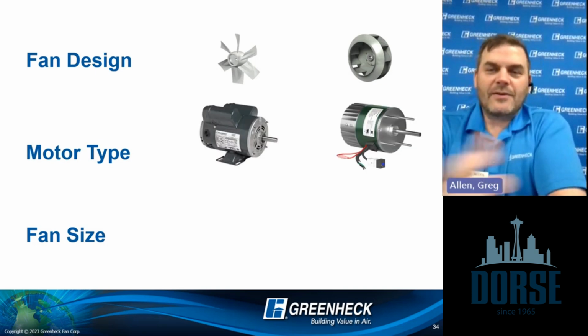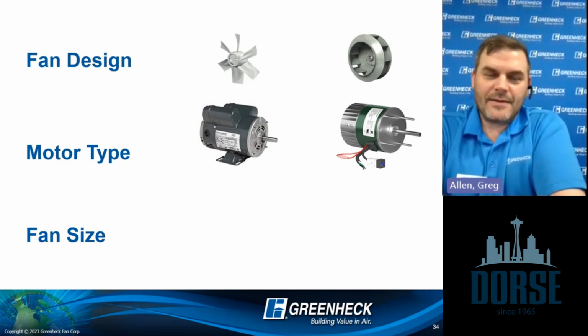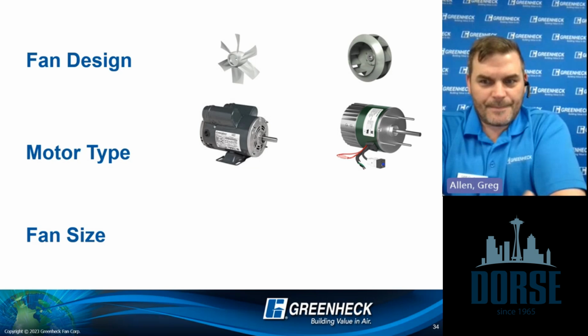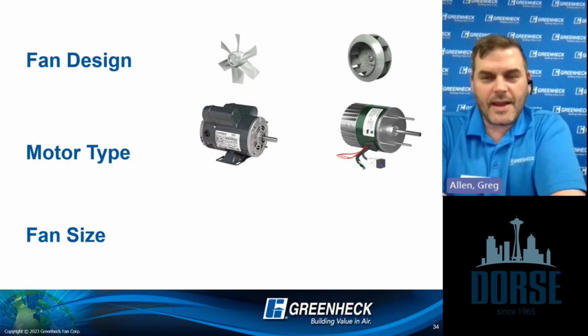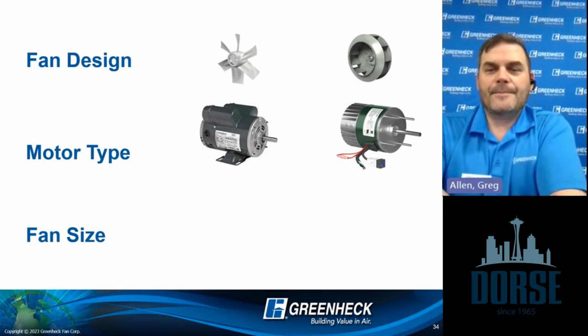In the single phase world, this is very evident. If I have a single phase AC induction motor, the motors are not very efficient, just by design. So in that realm, I'm showing on the screen an EC motor, an electronically commutated motor, which in single phase is sitting at 85% efficient. It's an extremely efficient design.